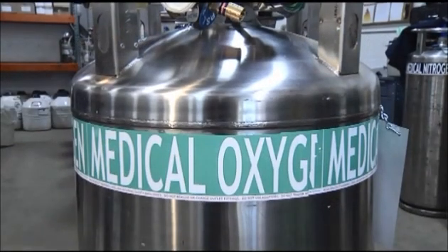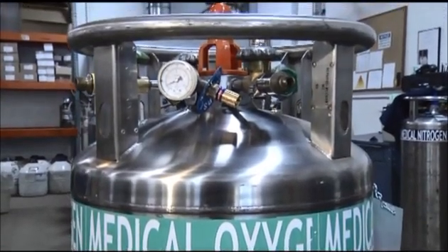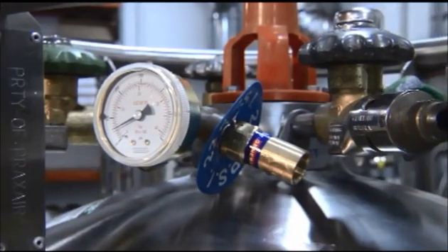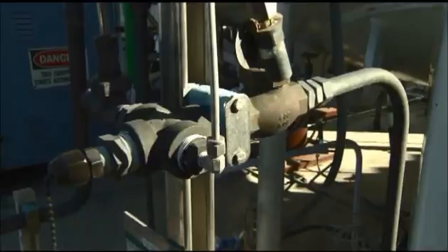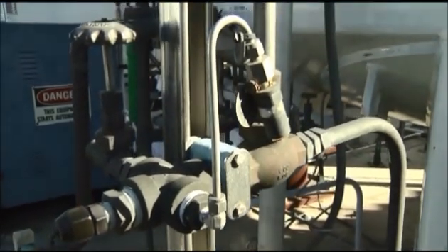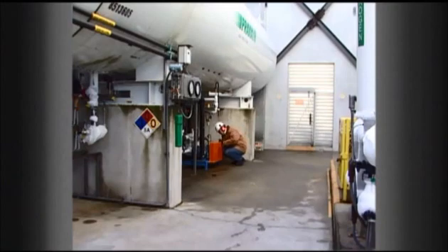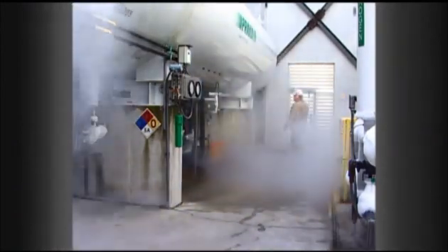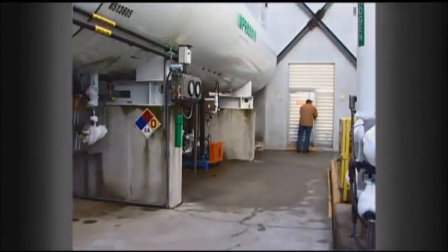For this reason, oxygen containers and piping systems are designed and built to strict specifications and include pressure relief valves that vent gas safely if the pressure rises too greatly. An accidental release of pressurized oxygen can propel objects through the air at high speeds, severely injuring a person working nearby. The cold vapor can also cause frostbite, which brings us to our next hazard.